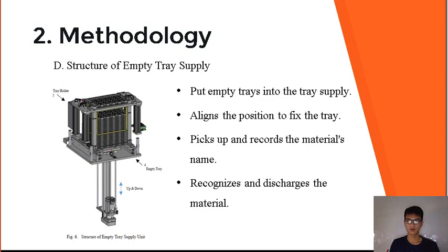When the designated number of defective materials is collected in the empty tray, the SCARA robot picks them up using the vacuum units of the transfer unit and records the defective material contained in the tray and the process information. Then it moves the tray to the next discharge conveyor and on to the next facility. The next facility recognizes that it is the defective tray with the information stored in the RFID and discharges it immediately.